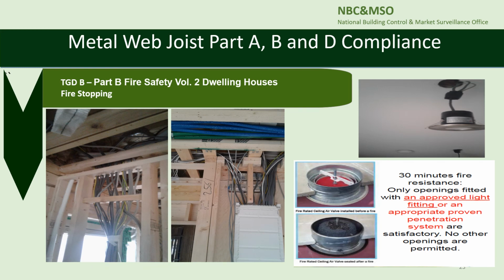This slide shows fire stopping items that designers need to consider as part of their compliance with Part B of the building regulation. Wires from the fuse board and downlighters and ventilation systems penetrating the floor or ceiling system.